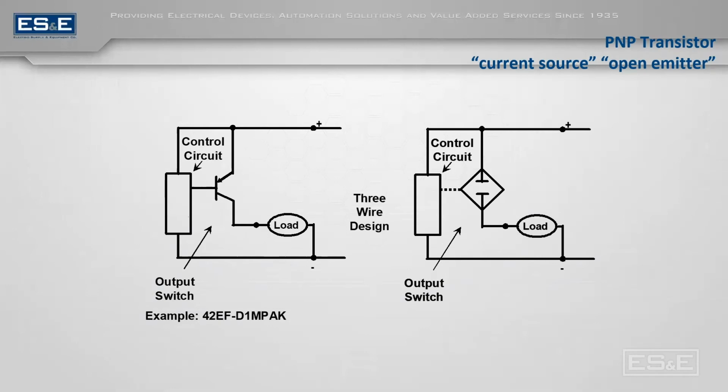A lot of sensors out there can be wired for either or, and some of the newer technology from Rockwell can actually automatically detect whether it's PNP or NPN. So you just use a single wire for whichever circuit and it picks the one it needs.